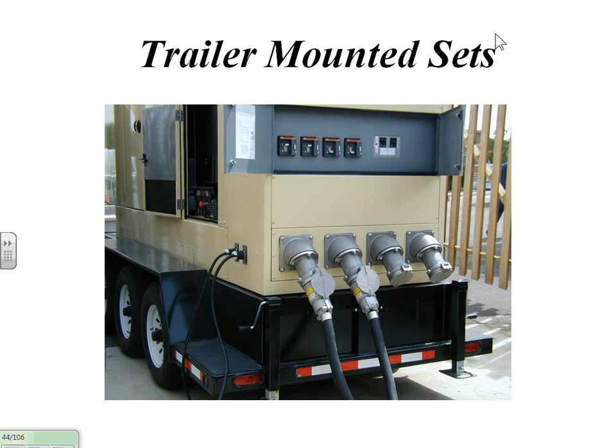Also, we have trailer mounted sets. This is a set I built for the city of Edina with a Kohler generator set. Cities like to have different voltages at a lot of different places, so they'll put on a big switch. We take a 12-lead alternator, the generator end, and we'll switch between the output leads in different configurations and make different voltages. And we can plug in certain lift stations. They might have a well that they need to back up, or they might have lift stations, so they might have different voltages on these different plugs. And I've got breakers up here for the different voltages when we switch to them.